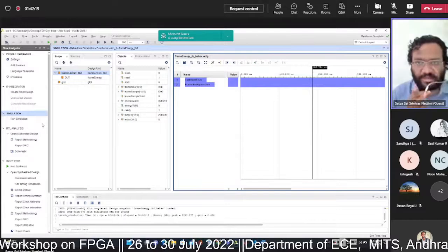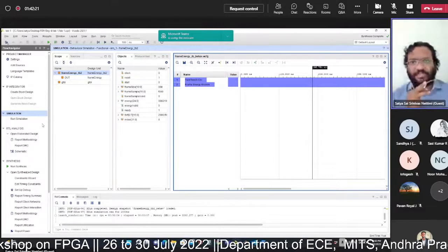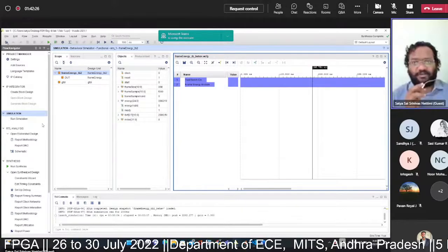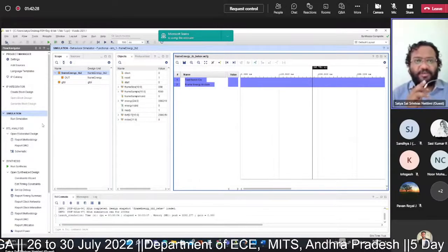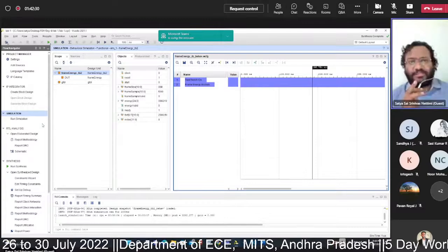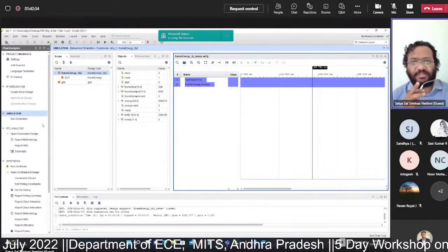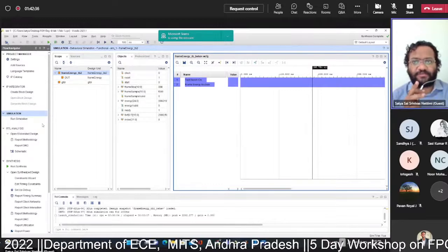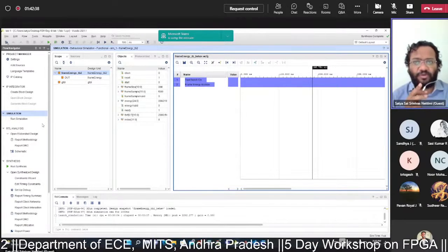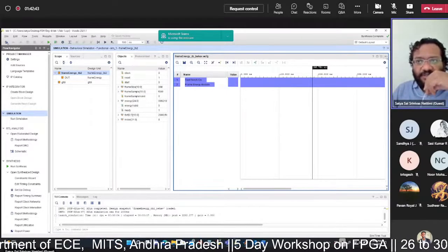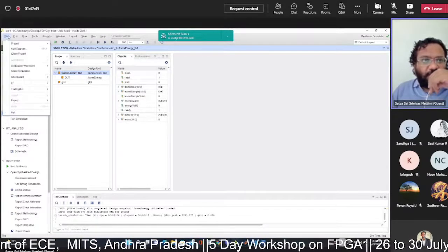But if you open this waveform configuration file with the first test bench, you can see the timing waveforms with the pre-saved settings. If you try to launch the simulation in the old waveform configuration file, then whatever the settings that you made with respect to your first test bench, everything will go. So that's why I will close this and click on file.